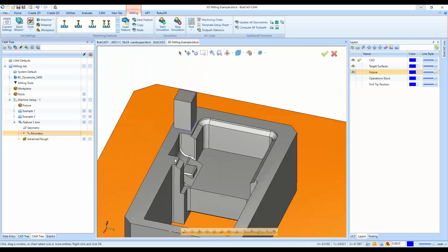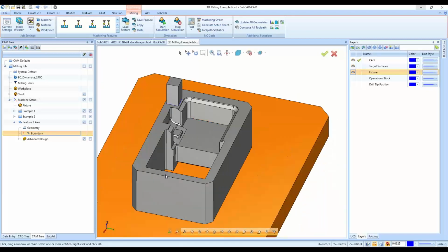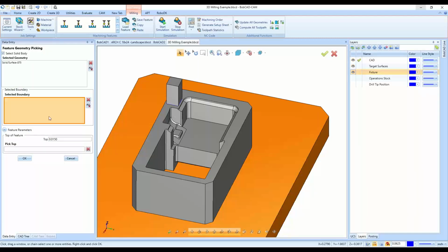and I can go over this topic that I went over last week, but it's very useful here, especially when selecting a boundary. Right-click, go to select, and I can right-click on an edge of a surface. So this kind of goes away from extracting the edges there for other layers. As useful as that can be, this is also very helpful where I can right-click on a surface, and there are two options. We have constant Z and loop selection.